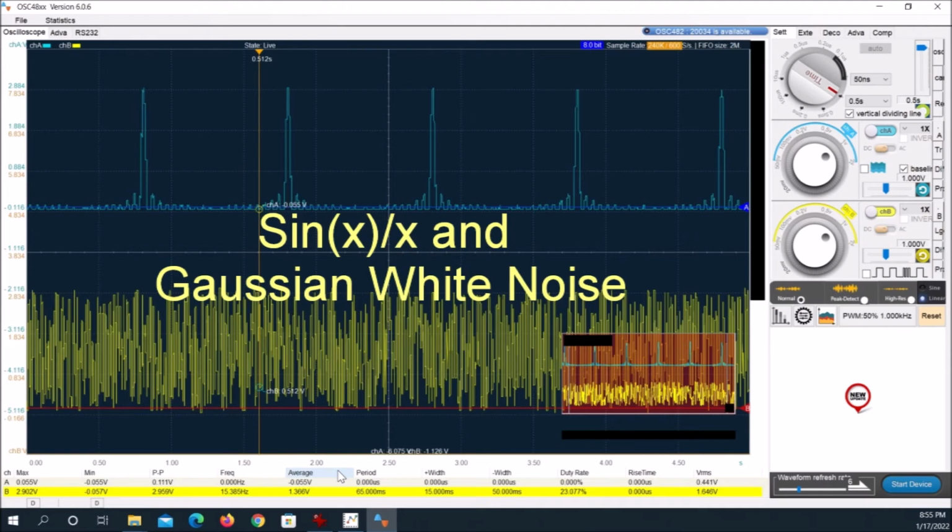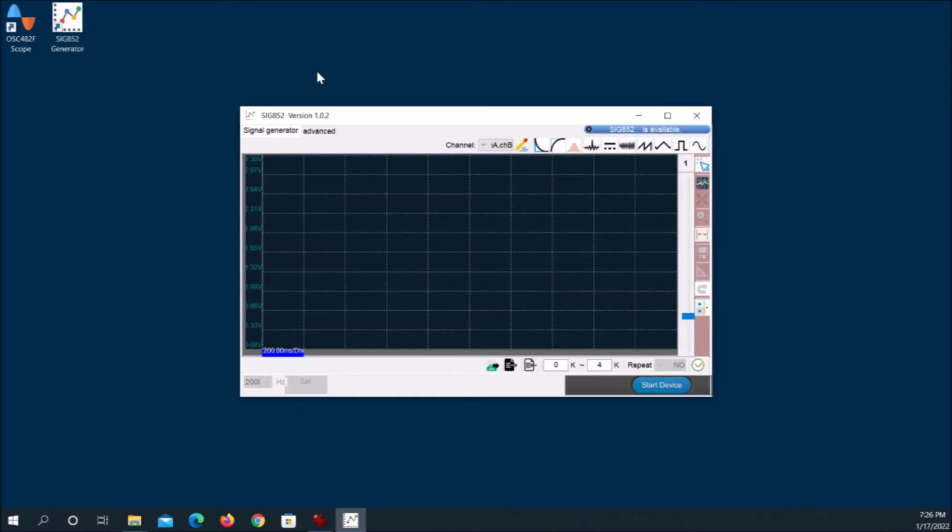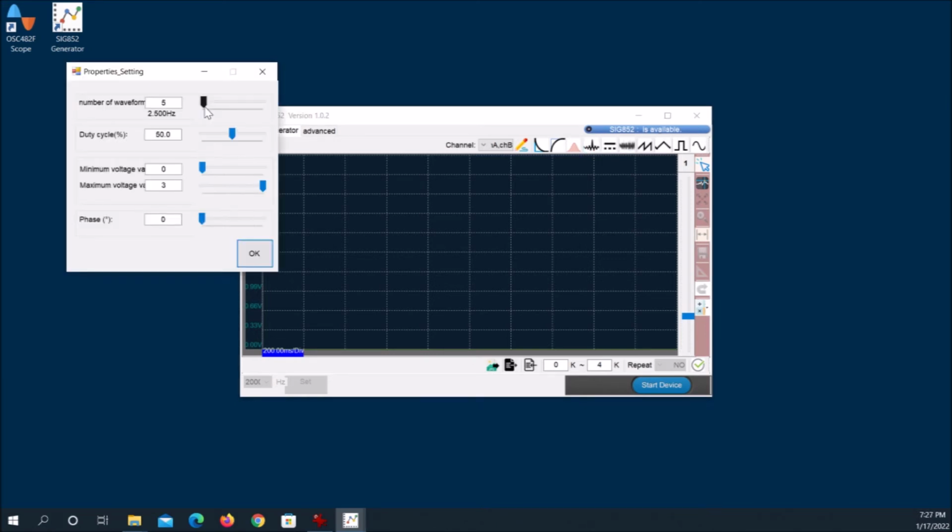The SIG852 has 2 outputs, channel A and channel B. Both have an on-off button switch and an LED. A small green removable jumper clip on each output channel enables an RC low-pass filter. These filters have a 30,000 Hz cutoff frequency.